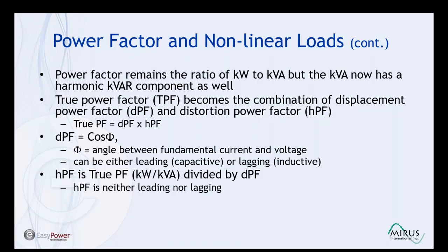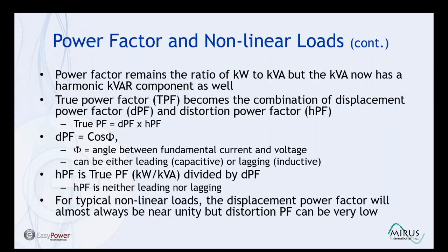Distortion power factor is neither leading nor lagging. Displacement power factor determines the sign of your total power factor. For typical nonlinear loads, the displacement power factor will almost always be near unity, but distortion power factor can be very low.